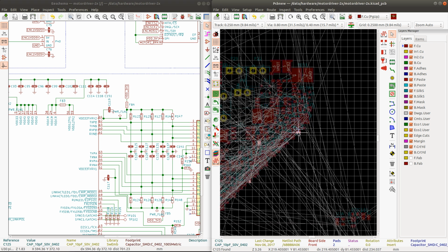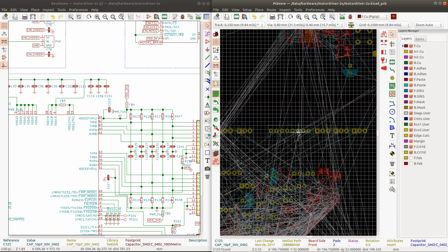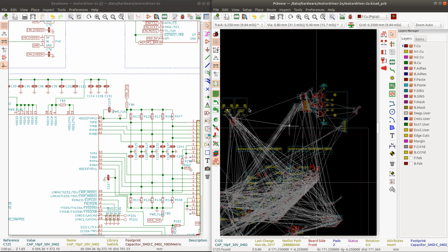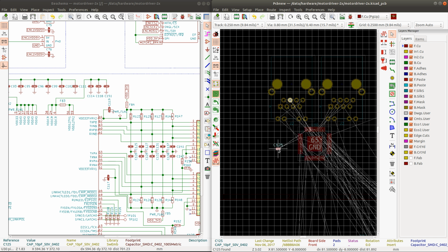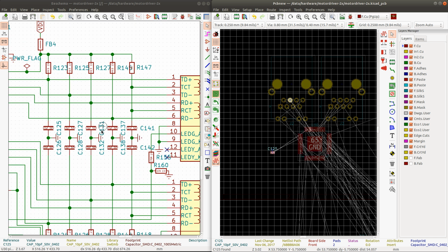So the Ethernet capacitors. Their function is to smooth out the slope. Let's see, there are 10 picofarads. Placing a capacitor between 10 picofarads to maybe 1000 picofarads is usual. The reason for usually placing that to ground is to smooth out the slope of the signal, because the radiated electromagnetic interference from a trace is proportional to the slope of the signal.